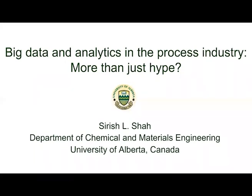Sirish, we have one more question submitted in the chat box: please could you talk about reducing variables in the analysis? What care should be taken to do so? So, if I can repeat, how to reduce variables in the analysis? Sure, good question. I think this is related to causality detection, whether it be process variable data or binary alarm data. The reason to reduce the number of variables to analyze is that you need to shortlist, because the transfer entropy approach or any other causality, cause and effect analysis approach is very computer intensive, takes a lot of time. So you really need to shortlist variables.